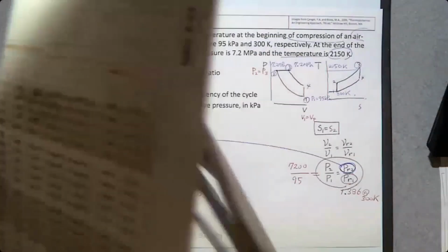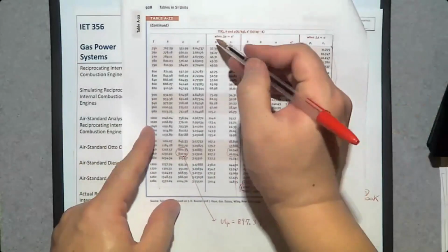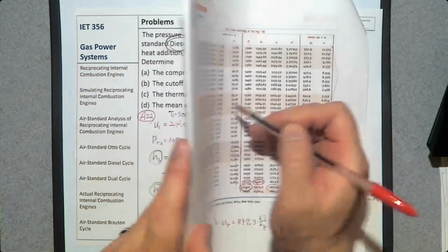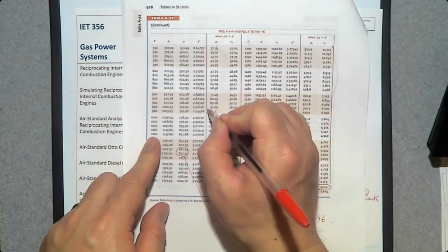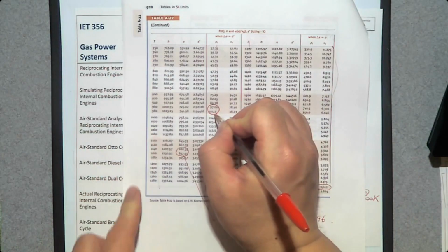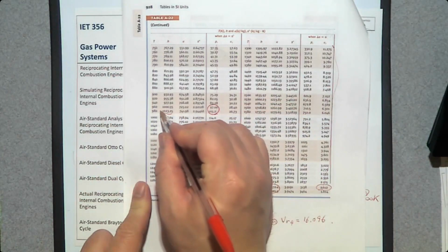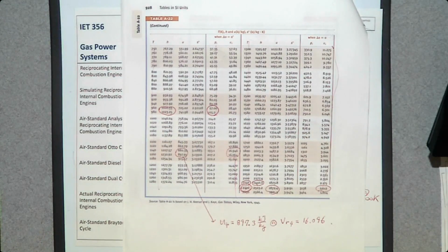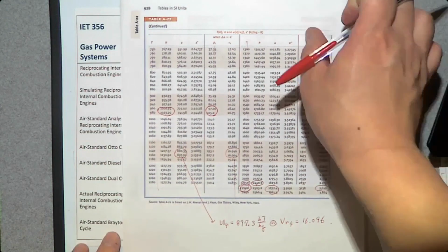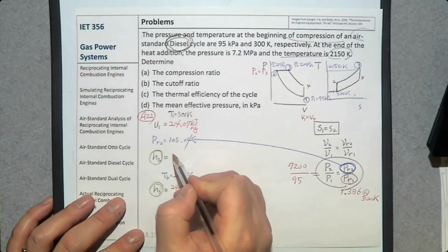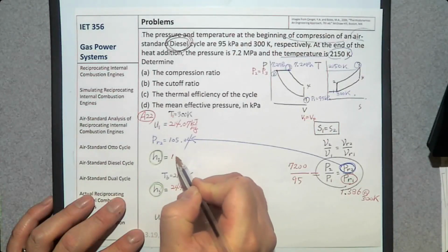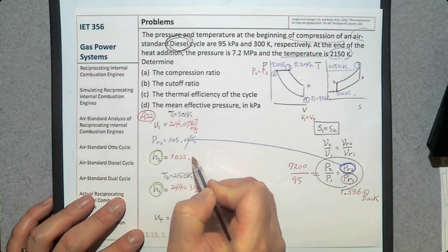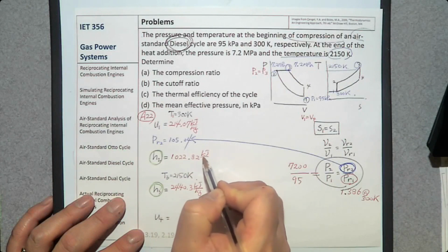Go to the next slide. PR 105. Oh, 105.04 is between these two numbers. So the H value should be between these two numbers. Then how can you find H2? Linear interpolation. If you do linear interpolation, you get H2, that is 1022.82 kilojoule per kilogram.